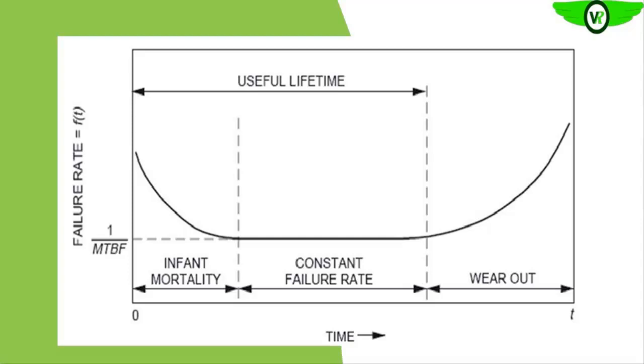So when the equipment goes into service, you see that after some time it will bed in, and then the probability of failure will stabilize over the operational life of the equipment. So any failure that occurs here will probably be due to maloperation, you operating the equipment wrongly.